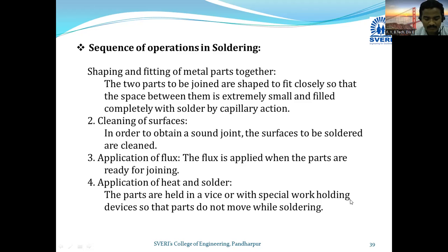Second step: cleaning the surface. Then third: application of flux. You have to apply the flux. Then next: application of heat and solder.